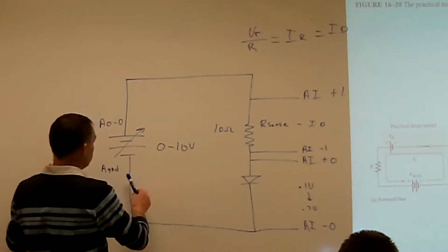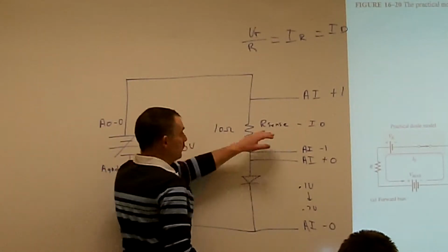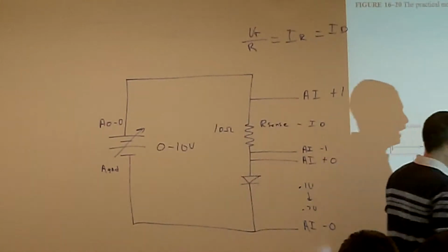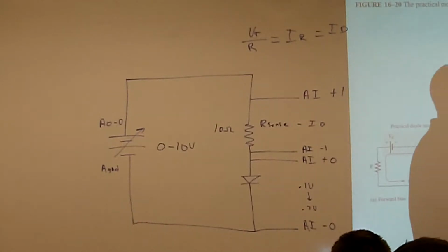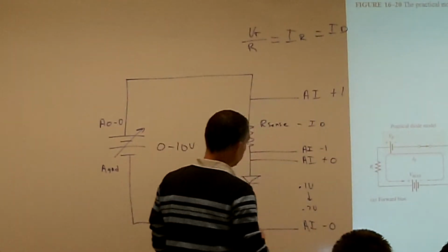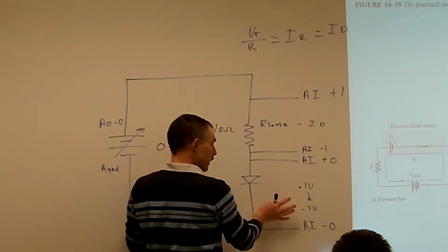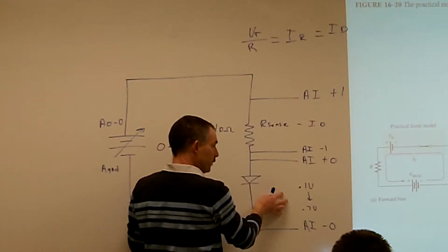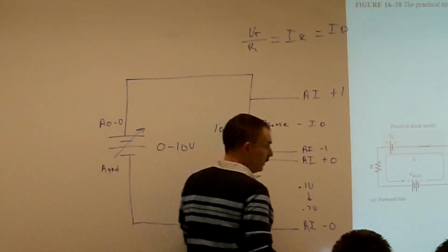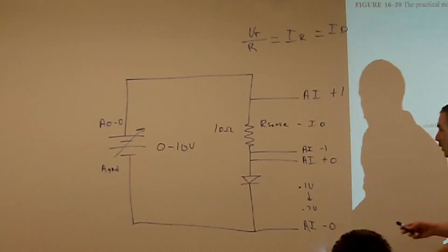And then it's going to stop. It's going to measure the sense resistor, calculate out the current, and then right at this point here, at 0.7, this is going to be right where it's going to start to increase. Okay, so exactly on our ideal model, at 0.7 volts, if I'm measuring 0.7 volts across my diode, I'm just about ready to start to turn that diode on.